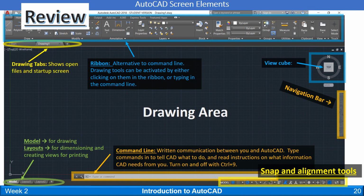Okay, just a recap of what we went through. So we started looking at the drawing area. You enter commands through the command line and by clicking on buttons up here in the ribbon. And remember that anything you click on in the ribbon, it's going to start filling in code in your command line. So you're always going to keep checking back and reading the command line. We've got your snap and alignment and construction tools down here. We've got our model space and our layout space. We'll look at layouts later down here. We've got all of your open files up here, ViewCube, navigation bar.